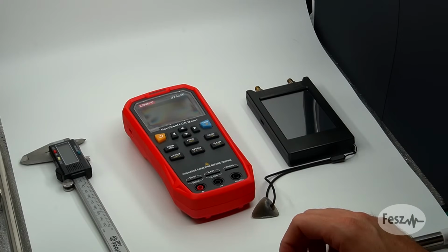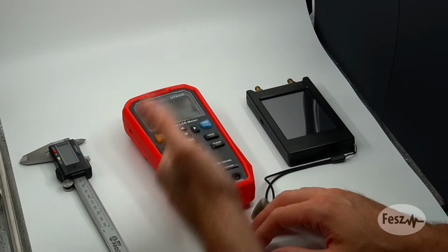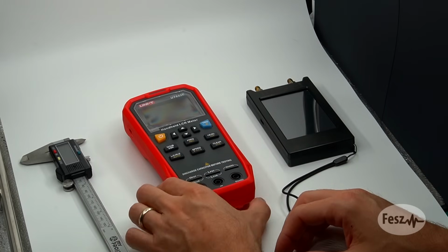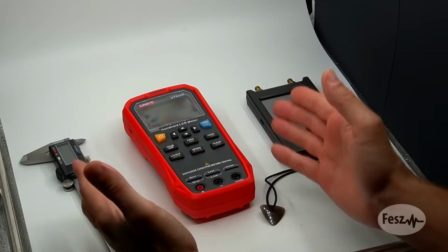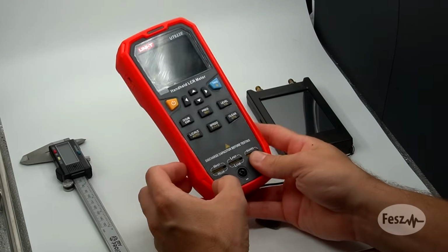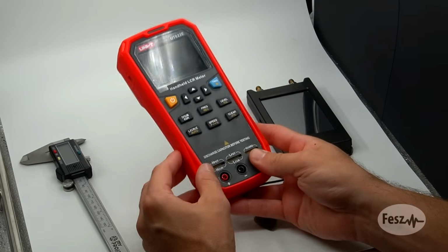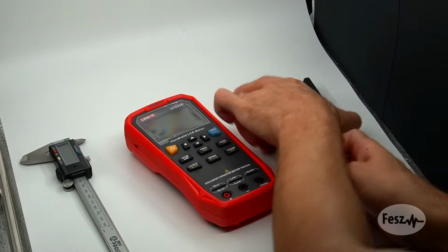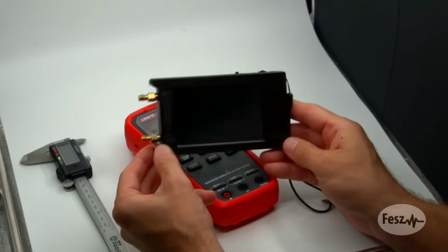So there are three main tools I will be using for today's measurements: a caliper, an RLC meter, and a vector network analyzer. Each of these has its own strengths and weaknesses. The RLC meter is special because it provides an easy way of measuring inductance at low frequencies. Each device is different, of course, but most common RLC meters work from about 100 Hz up to about 100 kHz. The VNA, on the other hand, while it's device dependent, will usually work at much higher frequencies.